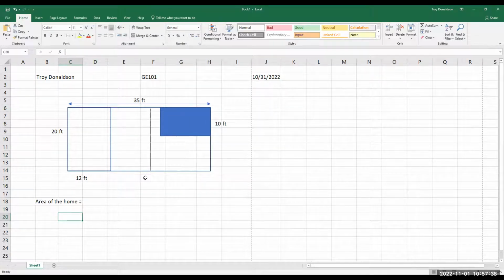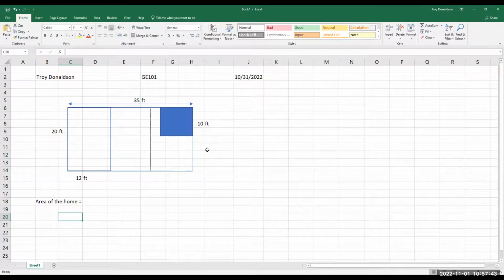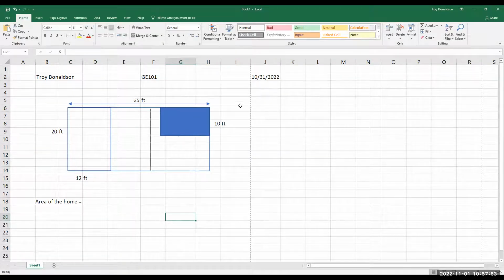And in this case, it's actually adjusting my diagram too, right? If I move things around, it changes the size of my diagram. So just be careful with that. Know that it's changing things. And as you do that, it looks like it's adjusting the size of the paper, and now my date went off the paper and I want it on the paper, so I've got to watch this dotted line too. To move it, I just highlight it, grab the edge.